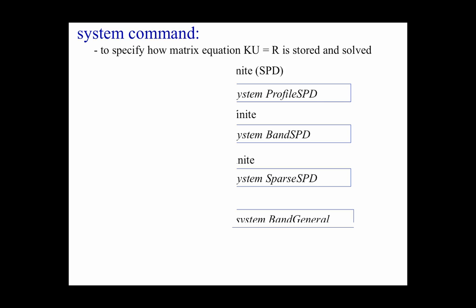What's wrong with using a sparse matrix solver for a small model? Other than the fact that it mightn't always pick up that there's a problem in your model. For example, you don't have enough boundary conditions, or you've specified a material with a zero tangent. Some of these solvers will actually give you a solution to that.